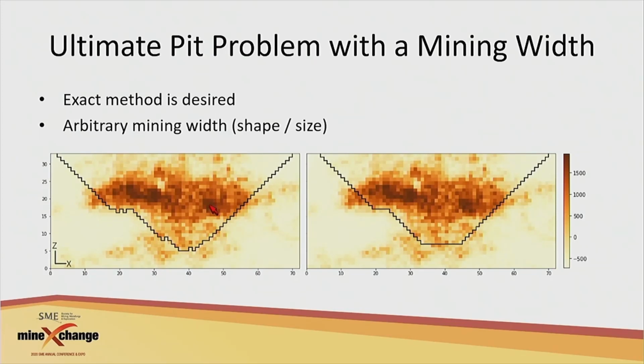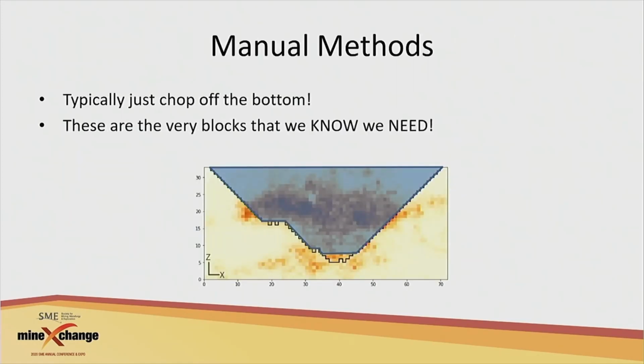And so then how is that typically done? How do people typically do this? Well, they calculate the ultimate pit, and then they'll just chop off the bottom, right? They'll just chop off the bottom when you're designing your pit at the end. You'll go down to some benches and you'll say, oh, it's too small. I'm going to go up a couple benches and start digitizing my pit starting here. Think about that for a little while. It's a little silly, right?